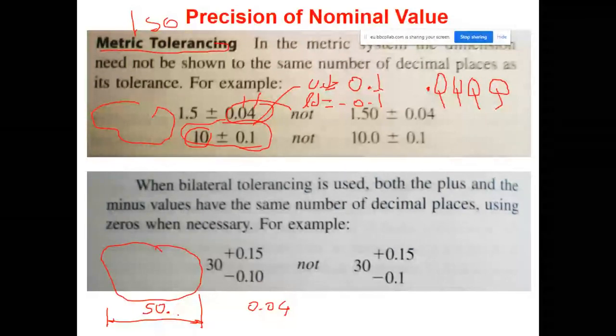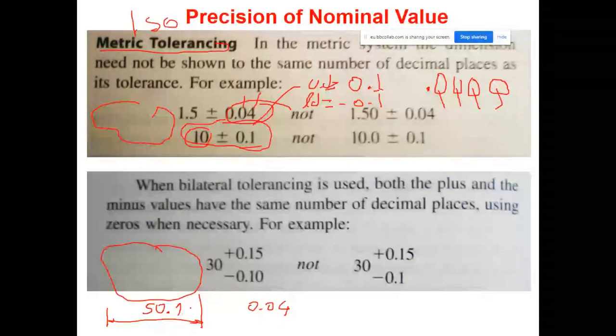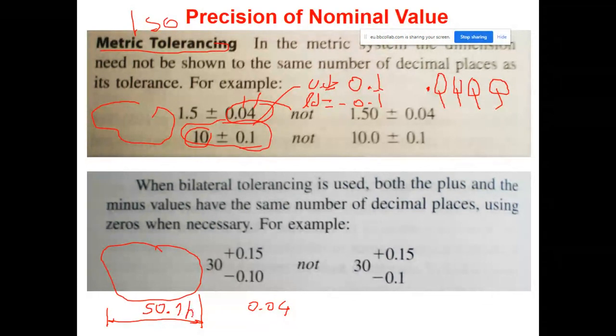What is the value of the figure? Well, in this example, let's say 1. Show the nominal value like this. And then the rest, write the tolerance class. For instance, it is H7.